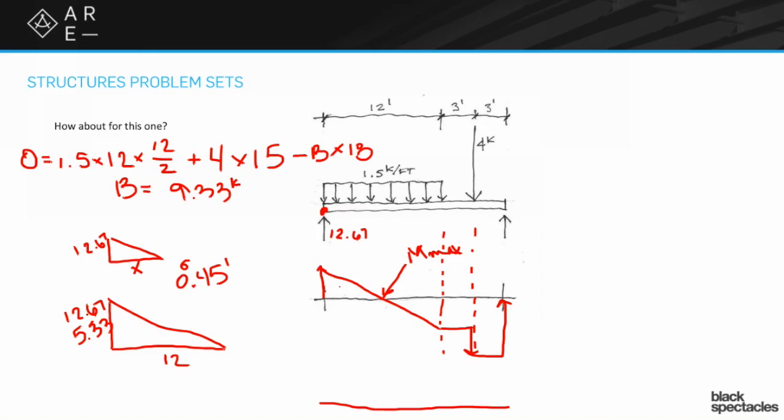Yep. So now, again, we have to think about that the point of moment is based on the area underneath this. And I haven't done this math, so I'm not going to really put values down, but I'm going to draw what the diagram looks like. Yeah, so this is just sort of approximate. Yep. So basically, because we have now a sloped line in our shear diagram, the line in the moment diagram needs to be a curve. So it's going to come up here and it's going to peak basically right there. And we happen to know that because we've already figured that out. Yep. So then it's going to start coming back down on a curve. Oop. Bad curve, but a curve, okay.